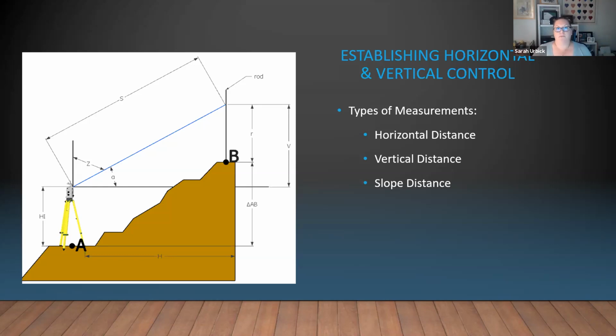The slope. So slope distance always kind of threw me a little bit. One thing that drove it home was when you drive down the freeway and you see all that nice, neat landscaping going in on Highway 1, around Mission and Emmeline. When they go out and grade those slopes, we need to know what that distance is. We can't just say, it's that far away. It's not just a horizontal component. It's a horizontal and a vertical component.